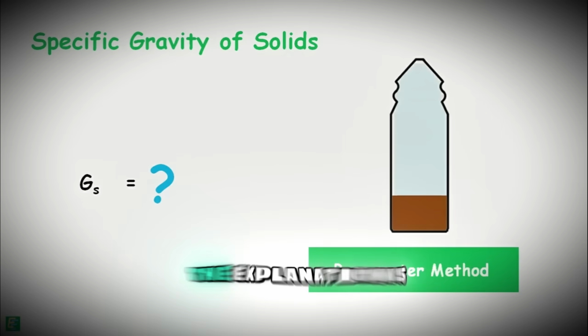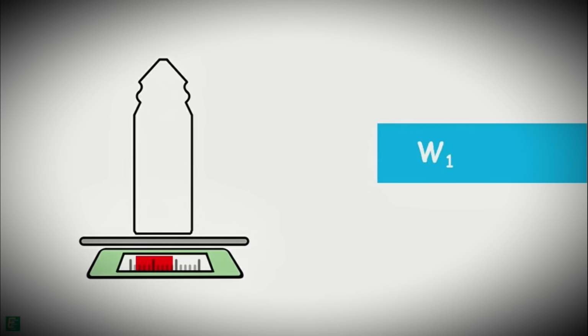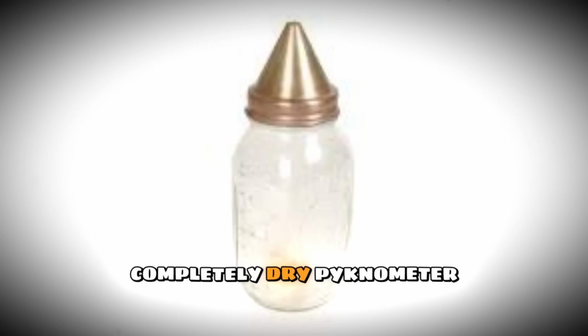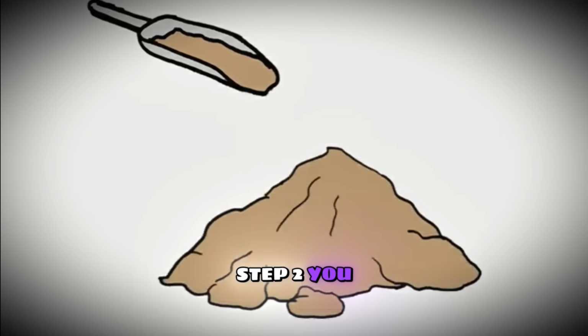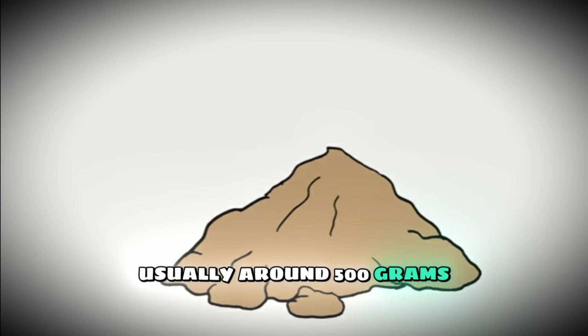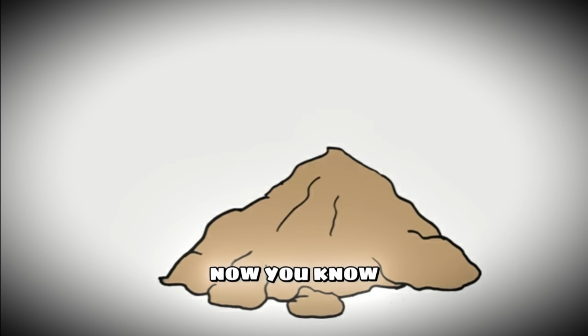The explanation is incredibly simple. We are basically doing a comparative weight test. Step 1, you take your clean, completely dry picnometer jar with the brass top on, and you weigh it empty. You log that number. Step 2, you take your oven-dried soil sample, usually around 500 grams, and you place it inside the jar. You weigh the jar again. Now you know the exact weight of your dry soil.